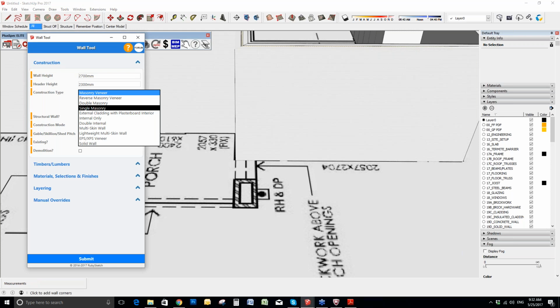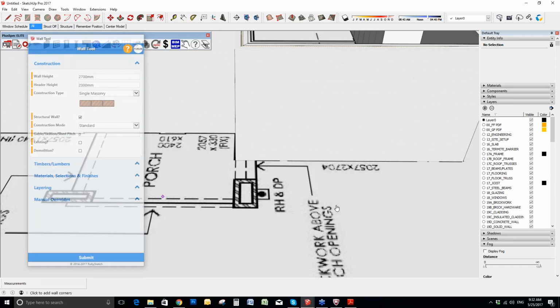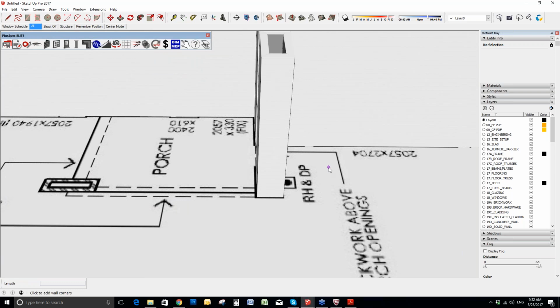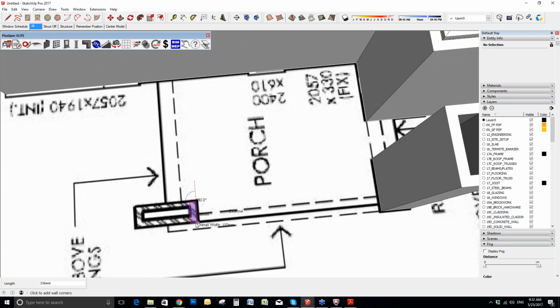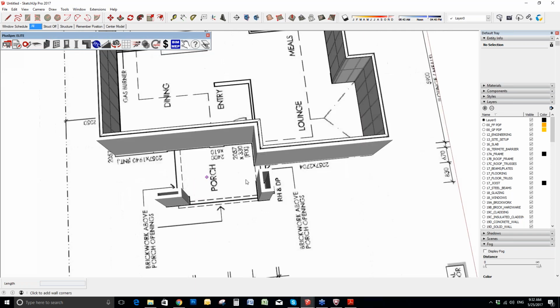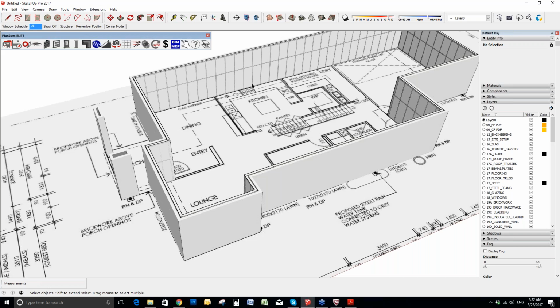All I'm doing is continuously looking at my project, making sure that I'm using the same materials and wall types, and now I'm just simply tracing. It really is that simple. Okay, there's that one. I'm going to do the same over on this side. Try to draw clockwise at all times. Hold down shift, it just means that you're going to be dead accurate. And I'm going around and tracing, so that's my first floor, or my ground floor, depending on your terminology.